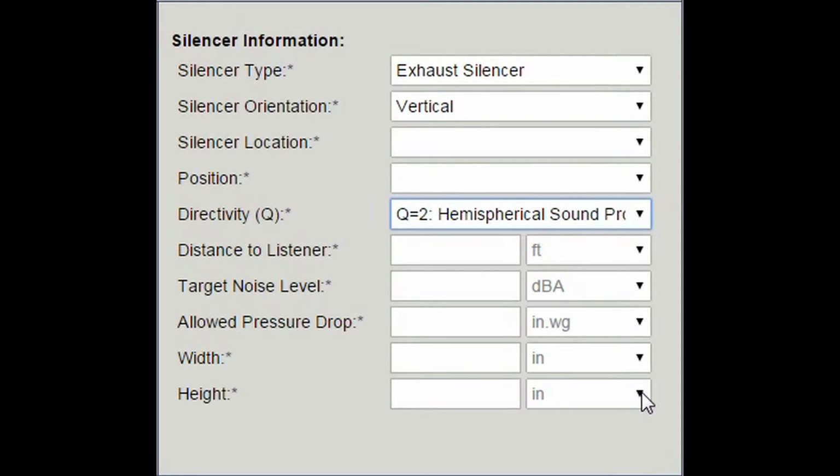the fan. Outlet height. This field label changes to either inlet box height, inlet height, or outlet height. This field is used to define the distance of fan connection to the grade. The entered distance is used to calculate the actual distance between the noise source and the observer, and to approximately size the silencer. When an inlet silencer is installed on the fan inlet box, height should be entered here. Furthermore, this field is also used to define the fan inlet outlet height, if the fan is installed on a platform or on top of another piece of equipment.